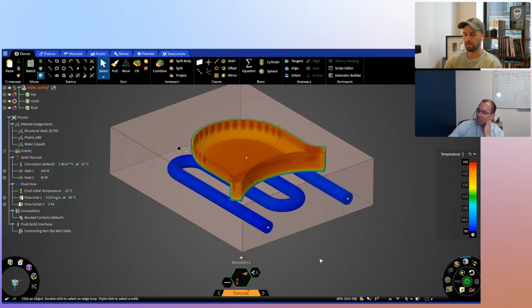Now, what I've done is I've pre-parameterized the model. What you just saw was a very interactive, very dynamic way to update the model so I can do a what-if scenario. But a lot of times what we're doing is a more structured what-if. You've probably heard the term I'm about to say: in some cases we call it a design of experiments, or DOE, where we've got multiple variables. Each variable has multiple options or variations, and we then create this multidimensional matrix, okay?